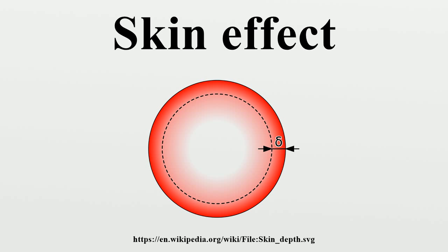In high current situations where conductors may be between 5 and 50 mm thick, the skin effect also occurs at sharp bends where the metal is compressed inside the bend and stretched outside the bend. The shorter path at the inner surface results in a lower resistance, which causes most of the current to be concentrated close to the inner bend surface. This will cause an increase in temperature rise in that region compared with the straight area of the same conductor.